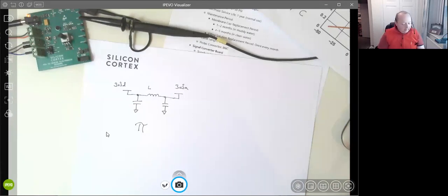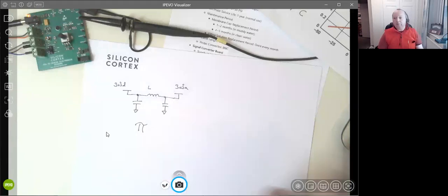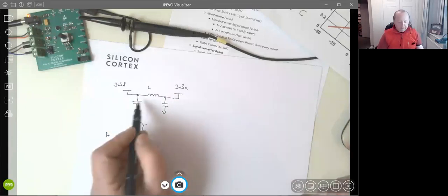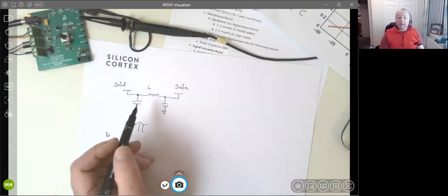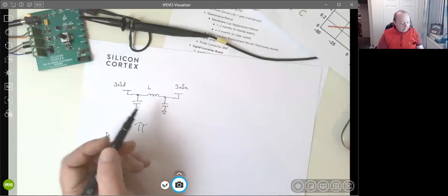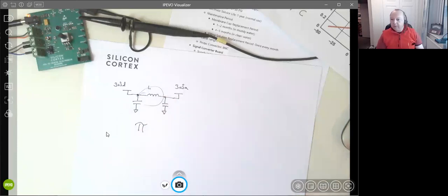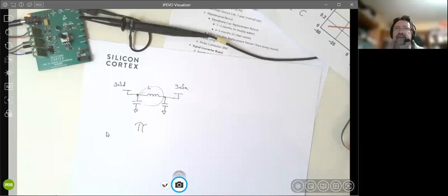So absolutely, John. If I'm taking any power off board or to sensors in my designs, like for accelerometers, for example, which is basically an analog device, a micro electromechanical device, then I will probably use a proper inductor for sure. So yeah, good point.